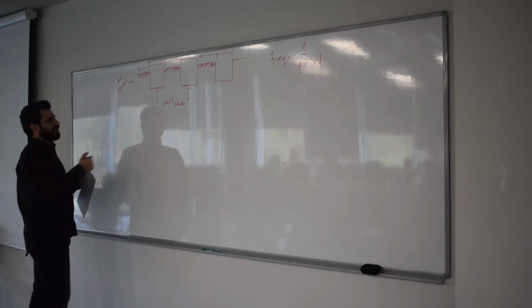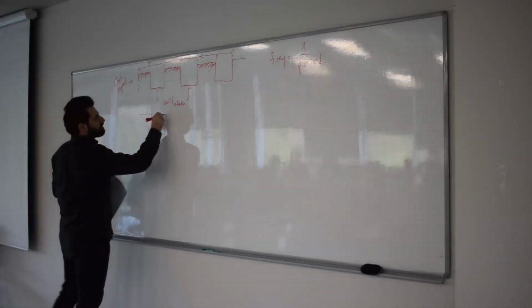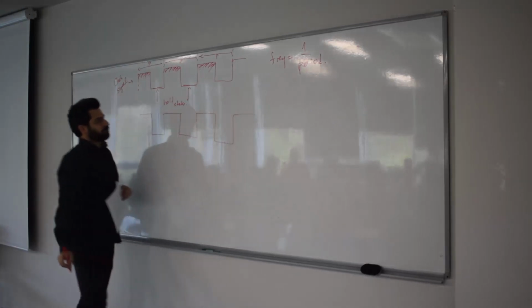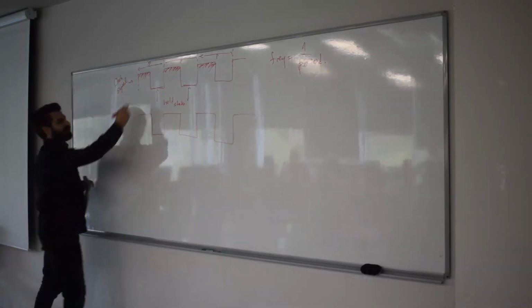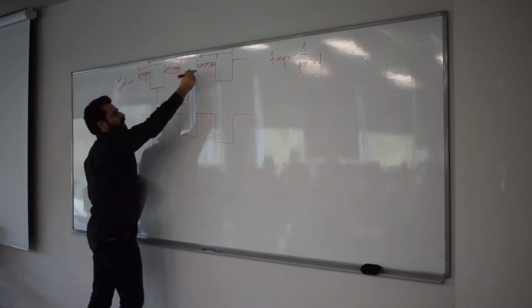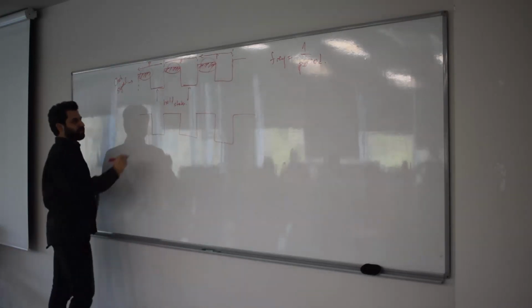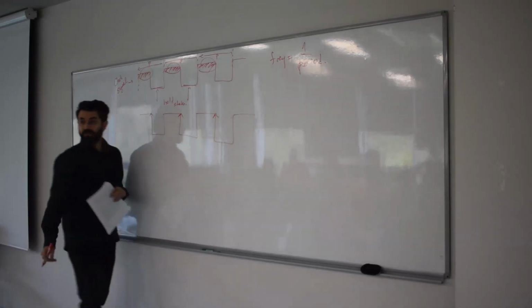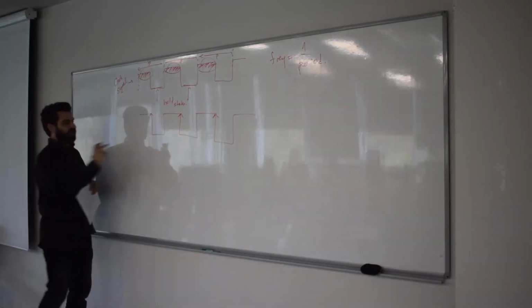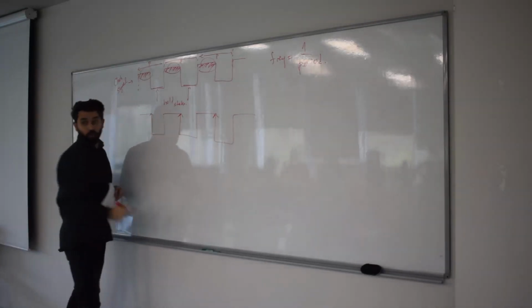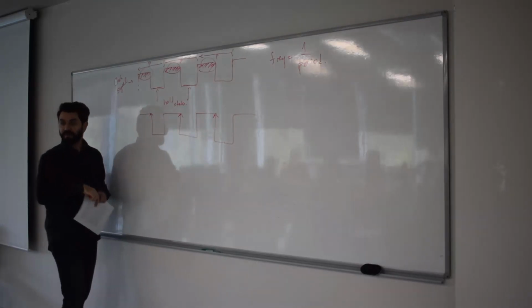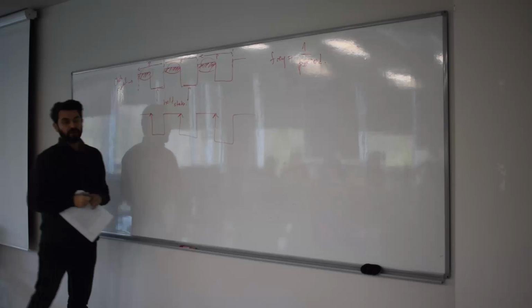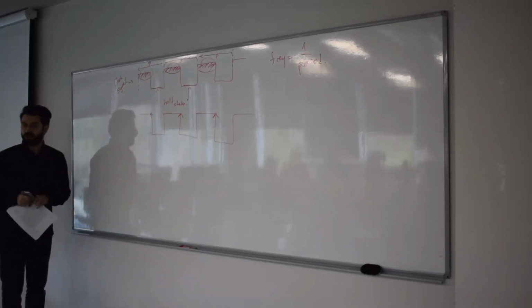What is changing in a flip-flop? I still have the same clock signal, right? Now instead of having these time periods, I'm interested in the rising edges, for instance. So the flip-flop can only change at those rising edges or falling edges, depending on the design, and I'll show you two different designs, one for the rising edge and one for the falling edge.